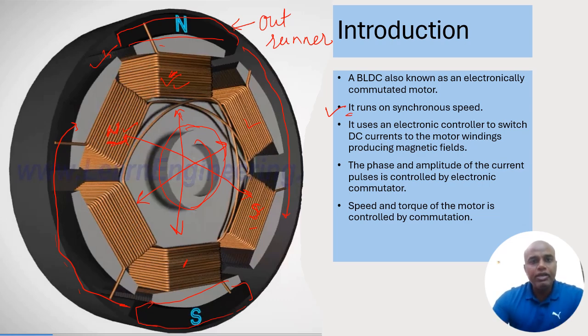Now here we need to pay attention that there are three windings energizing at different times, and it looks like the BLDC motor will have three wires and a fourth wire which is common for all three windings. So instead of a two wire system like in the brushed DC motor, the BLDC motor may have a four wire system. It looks like a kind of three-phase AC motor, but no, it is a DC motor, and DC supply is being given to the stator winding at different times by the commutation process.